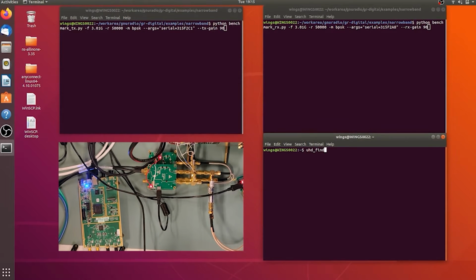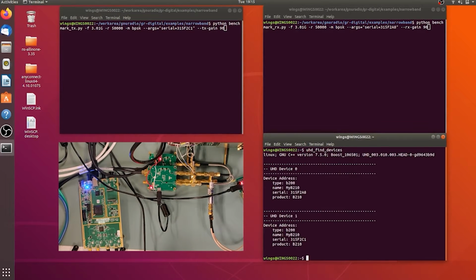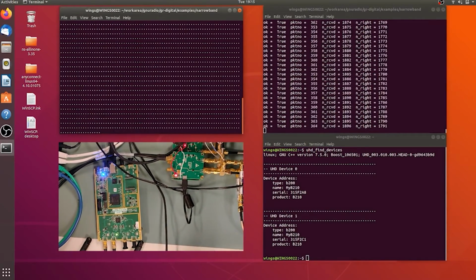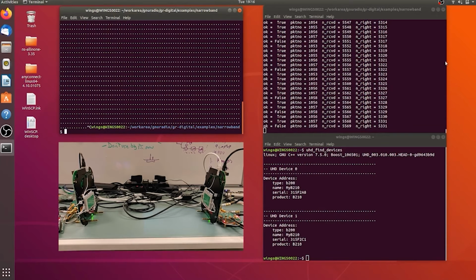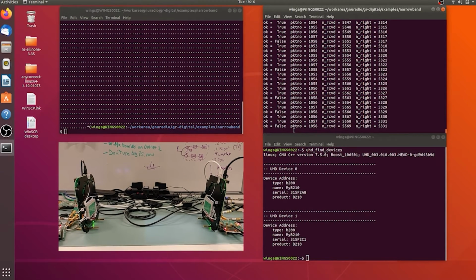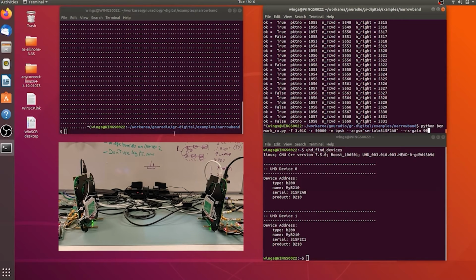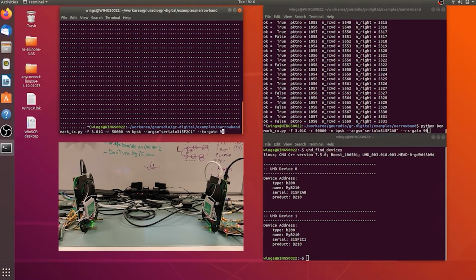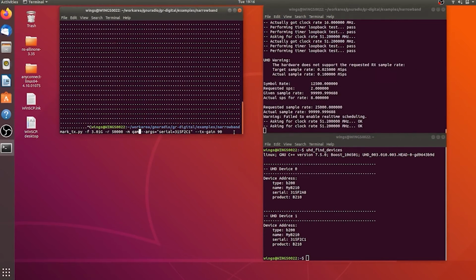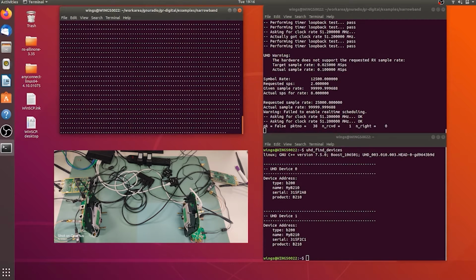Now that the initial setup is complete, we can demonstrate the communication using benchmark code. We are currently communicating at frequency of 3.01 GHz, rate 50,000, modulation scheme BPSK, and gain 90 dB to get efficient response and higher correct packets. We can see that by changing modulation scheme to QAM, there is a significant reduction in efficiency with zero correct bits transmitted, even with a very high gain.